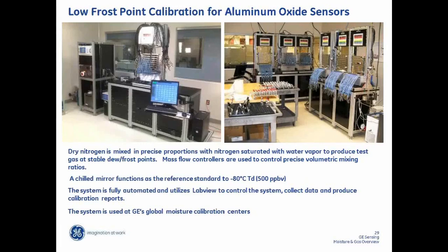In some applications, they refer to that as the process dew point. The process dew point is the combined effect of all the polar compounds. And very often that might be used because it's somewhat repeatable. But that's not the case here. The laser has the ability to discriminate between polar compounds and the water itself.